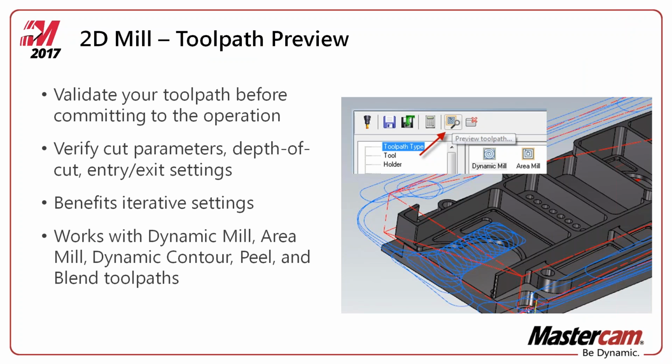Now back in X9, we put in some options as far as the preview toolpath. That was in your simple contours and things like that. And now we've put that into the 2D high-speed toolpaths as well.